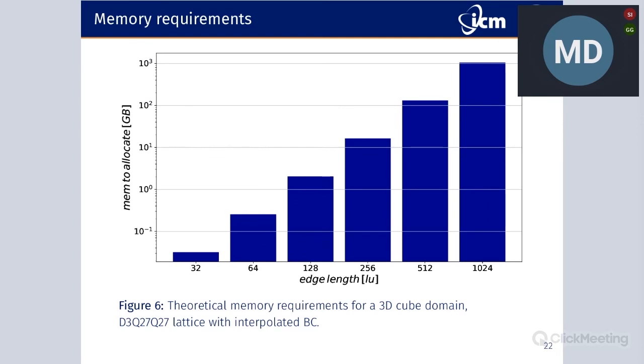So a single cube in 3 dimensions with 1,000 nodes in each direction is not very big, but it is almost a terabyte of memory. If you would like to simulate cars or planes, that would be 2 or 3 orders of magnitude bigger. So Lattice Boltzmann is rather confined to phenomena that could fit in thousands, so maybe 2,000.